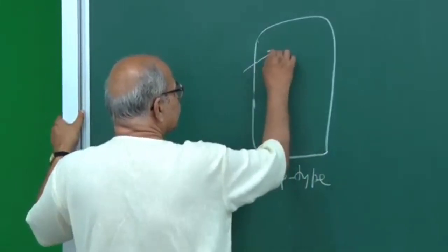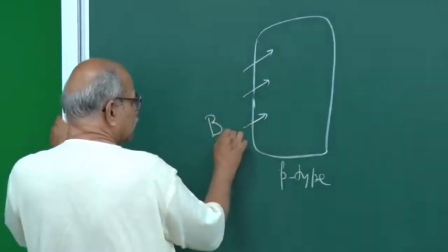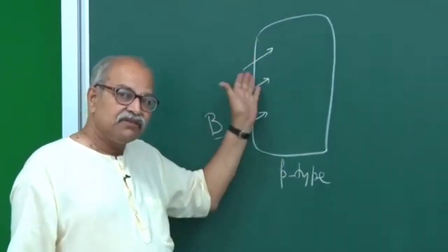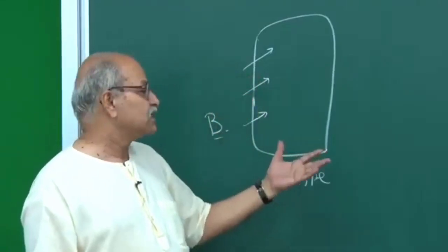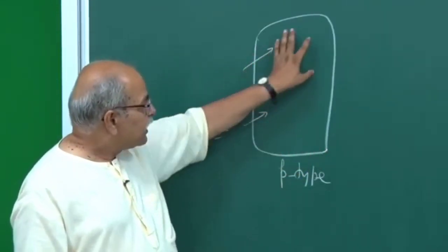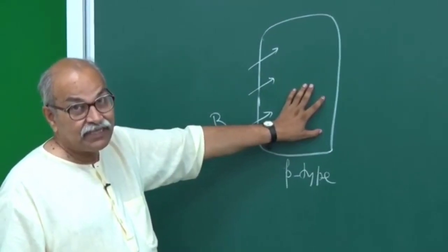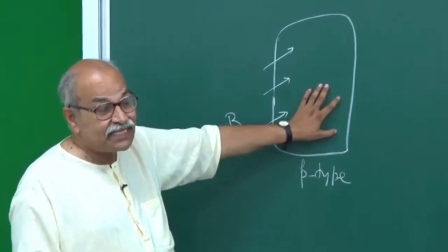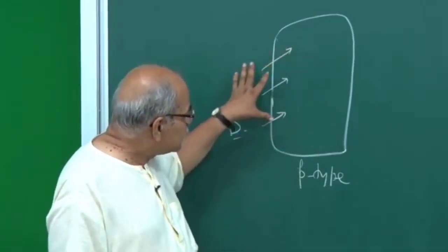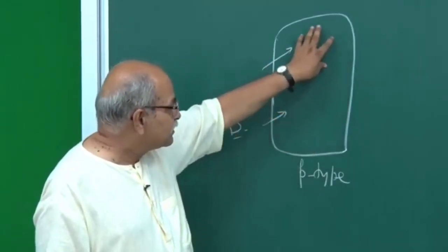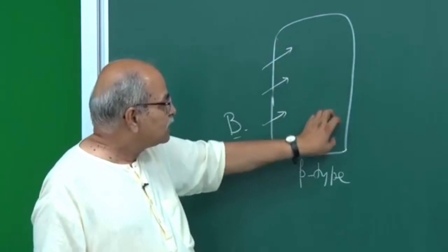To make it p-type, you have to diffuse a trivalent impurity like boron, so it goes there. Here also you have very controlled processes. There are several processes by which you diffuse these impurities, and at the end you retain that silicon crystal. Silicon I am taking as our model semiconductor. In any kind of semiconductor you have to do all this processing, and through very controlled processes, without finally disturbing that crystal structure, you have to put these impurities at those lattice sites.